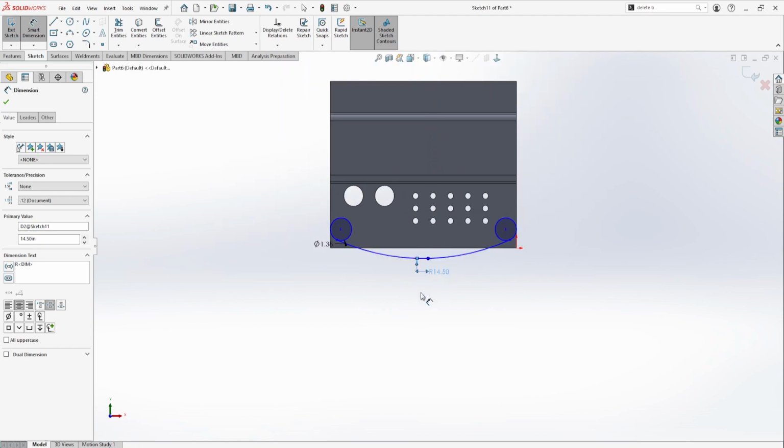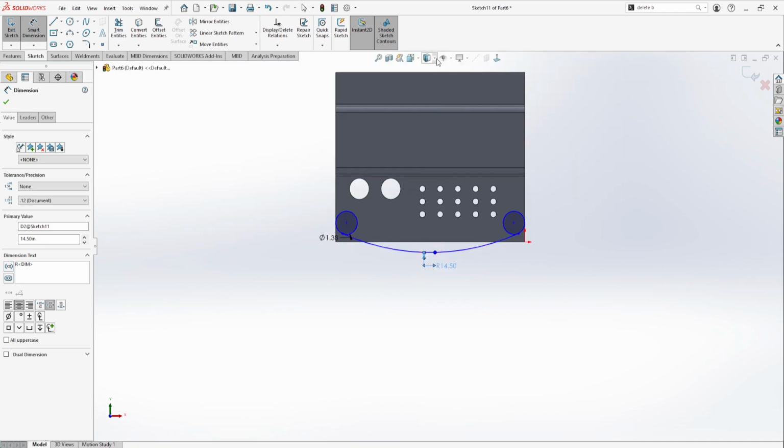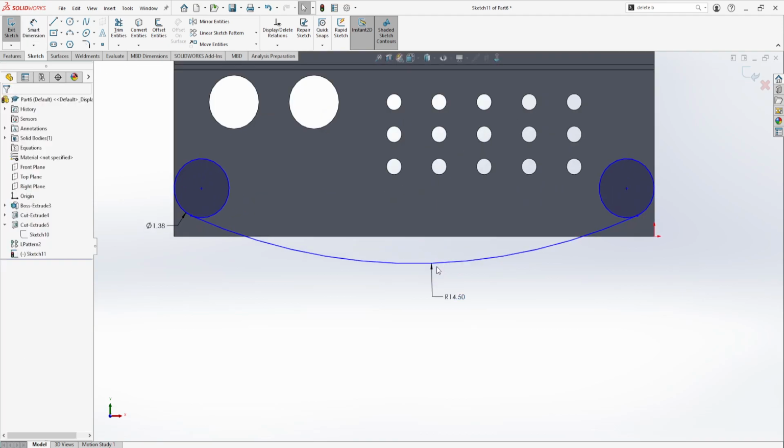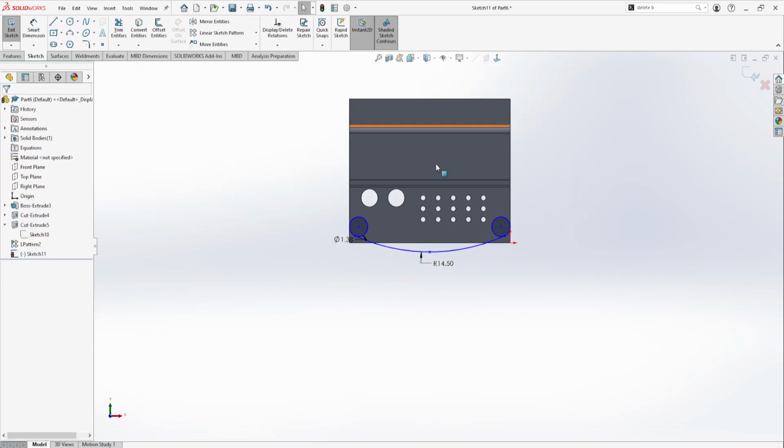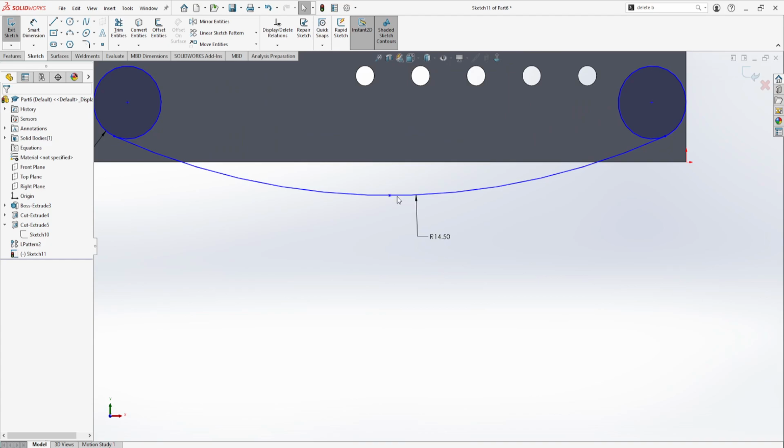And then in order to set this, we can either make this tangent to this face, or we could do a dimension from here to here. So that it's feature driven, we can go ahead, because if we did a dimension, if this part ends up changing, this would not end up staying correct if we change our numbers elsewhere.